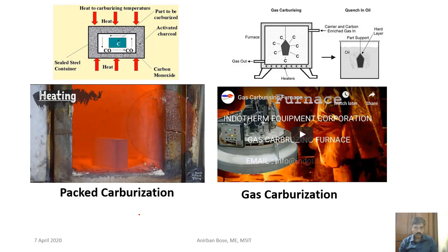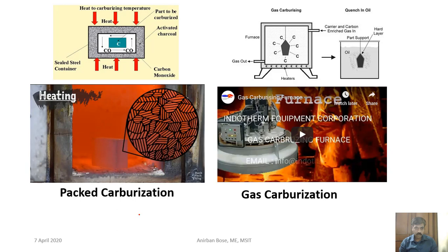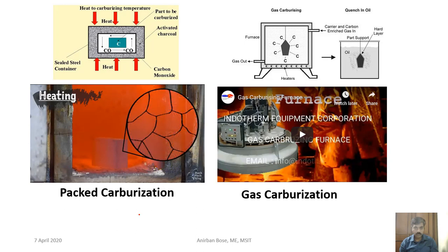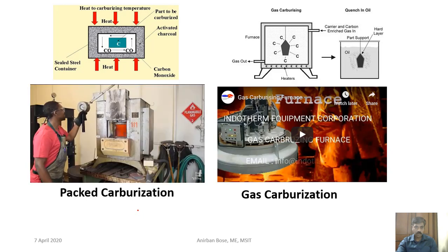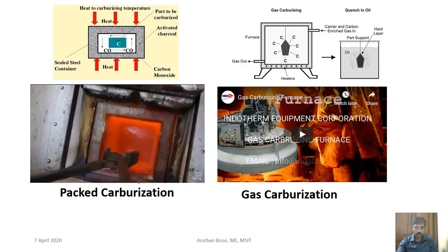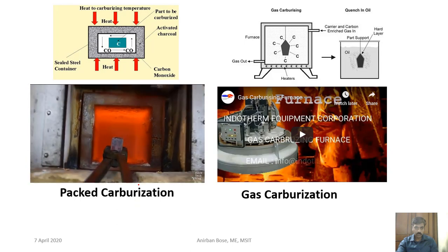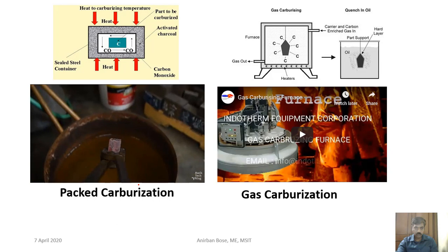At room temperature, the microscopic structure of the high-carbon steel is composed of alternating layers of iron and brittle iron carbide. This microstructure is known as pearlite. When the steel gets hot enough, the pearlite dissolves, and the microstructure transforms into a non-magnetic solution of carbon and iron called austenite. Once all of the pearlite is dissolved, it's time to quench. Pull the parts out with a set of tongs. Quickly plunge them into a container of water and agitate the parts in a figure-8 motion until they're cool to the touch.